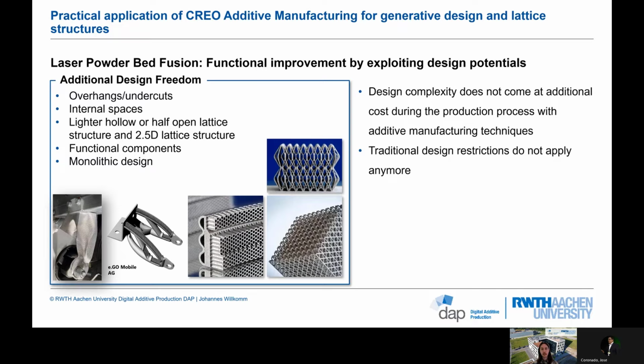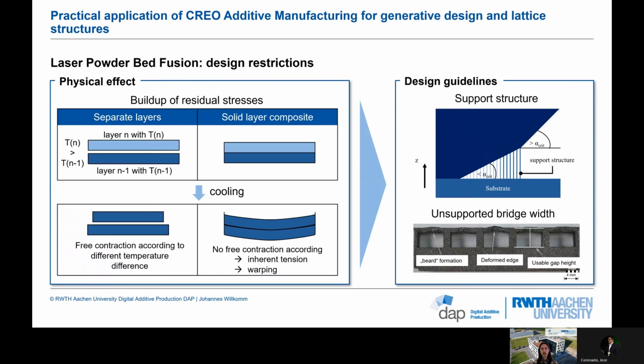And here you can see some examples of LPBF parts, like some topology optimized parts, some parts with 2D or 3D lattice structures. As you can see, it's not possible to manufacture these parts with traditional design or with traditional manufacturing methods. But also here in laser powder bed fusion, there is no complete design freedom. Besides some design restrictions like minimal size of a geometry feature,